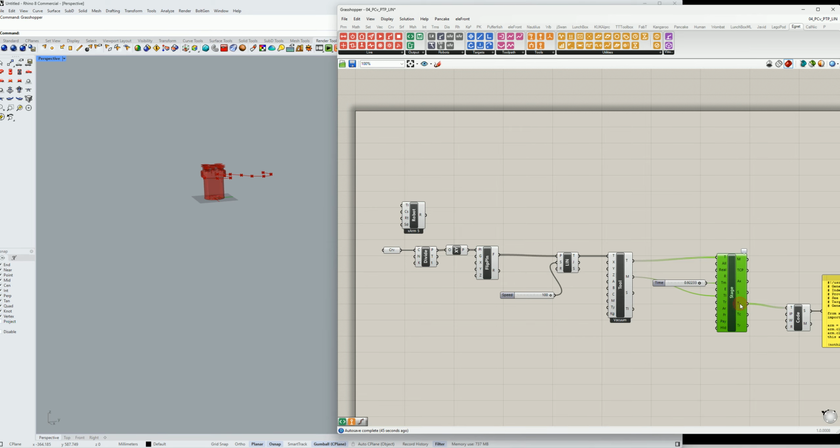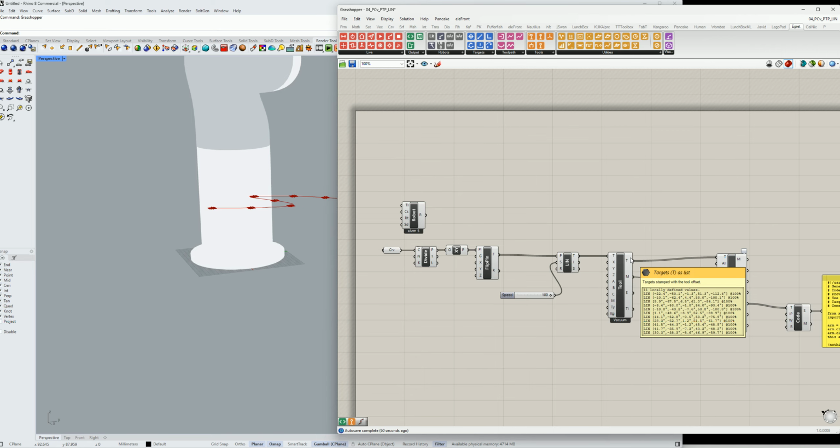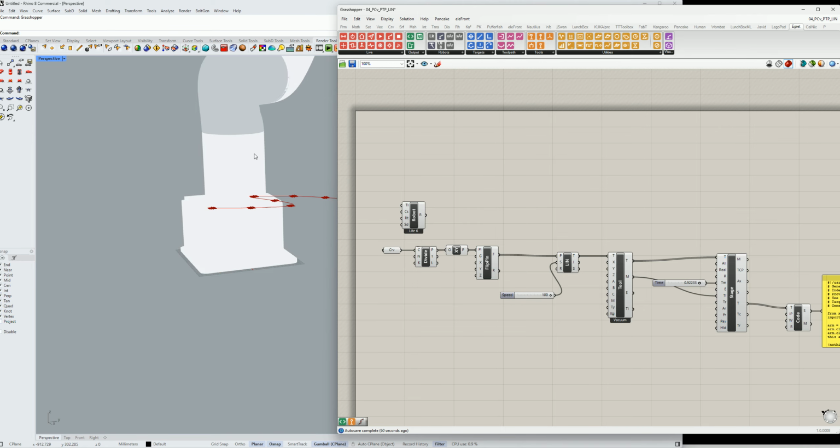If we hide this, you can see the mesh of the tool we want to use. So if you had a custom mesh, you want to align it so it's in the origin of the XY plane, and it gets mapped to the end of the robot. All right, I'm going to switch it back to the Lite 6 because that's what I have.